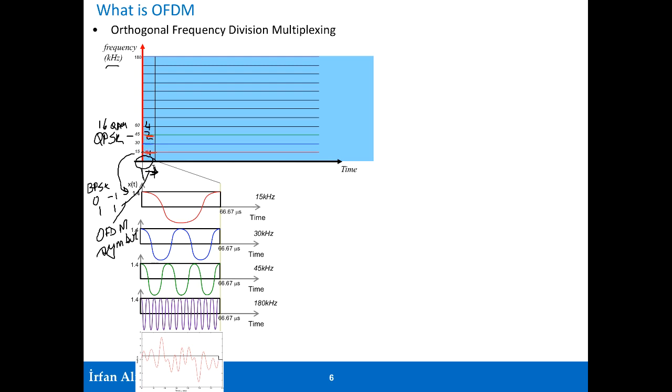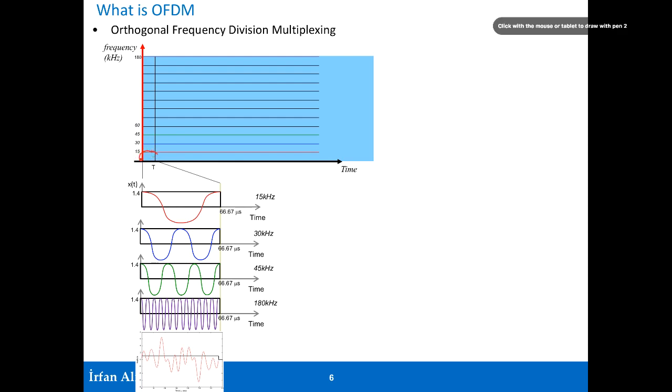So you're sending 1 bit or 2 bits of information, and the way it gets represented in LTE is that this particular box over here is called a resource element. It can carry either 1 bit, or 2 bits, or 4 bits, or 6 bits. 6 bits is 64 QAM, the highest modulation up to release 10, and beyond release 10 they've gone into even higher modulation.